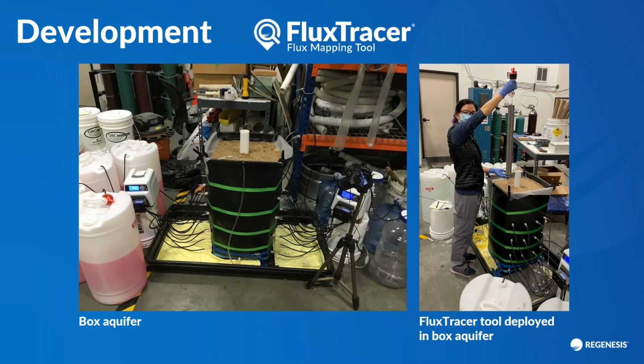Since I'm in R&D, I'd like to point out some of the development work that we did along with the devices. You've got a picture here of a box aquifer that we had to build, a test cell that we used to validate the flux measurements that we were making. On the left, you can see we had set up to do a dye test, a tracer test, to make sure that this test cell that we built had even flow across the entire screen interval that we had.